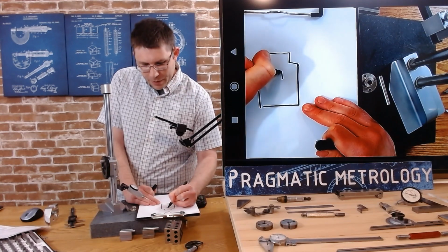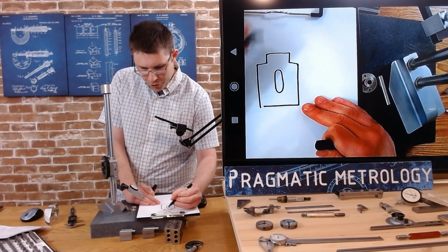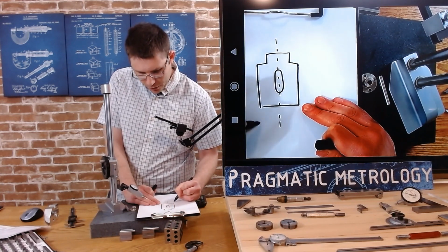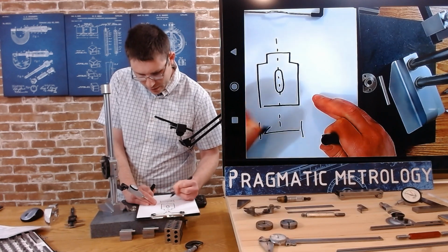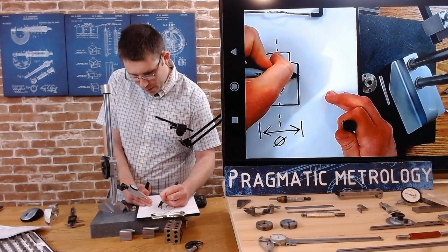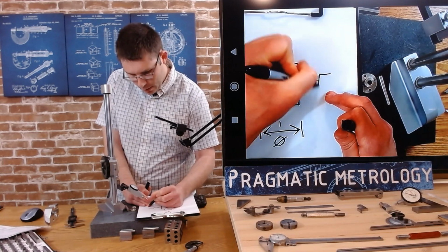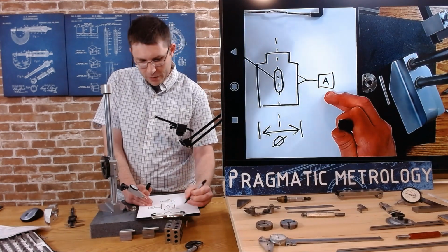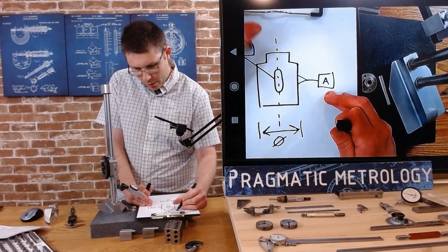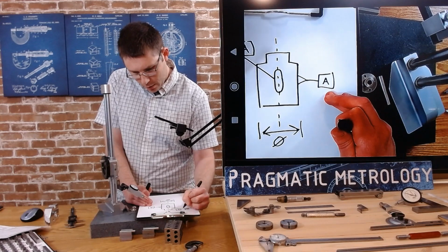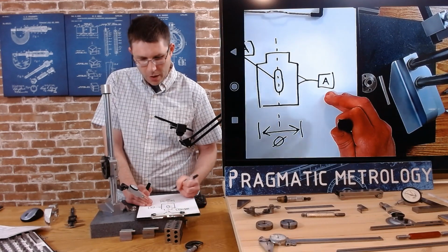You may need a keyway slot, and you may want it to be centered, and you may be defining this diameter as datum A. So you may want to control the size of this slot and the position with a true position symbol of, let's say, 0.01. We'll make it open tolerance.